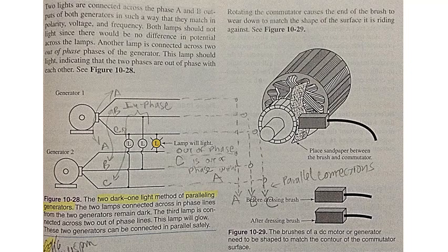This is very damaging to the self-excited generator. If the residual magnetism is lost, the generator will fail to build up sufficient voltage. Residual magnetism can be restored by connecting a separate DC power supply, such as a battery, to the field windings.